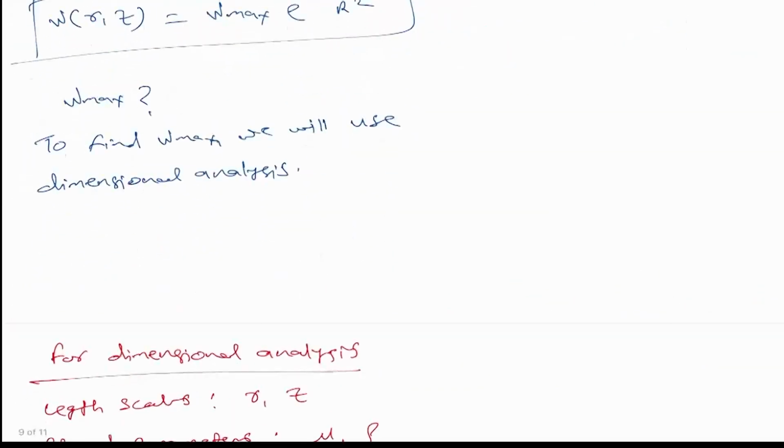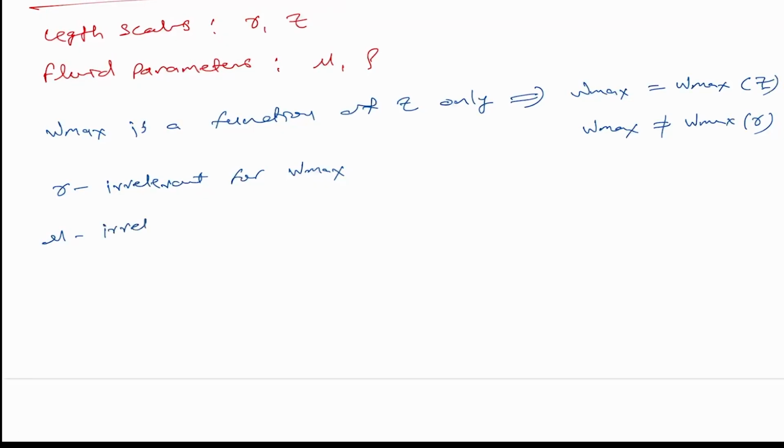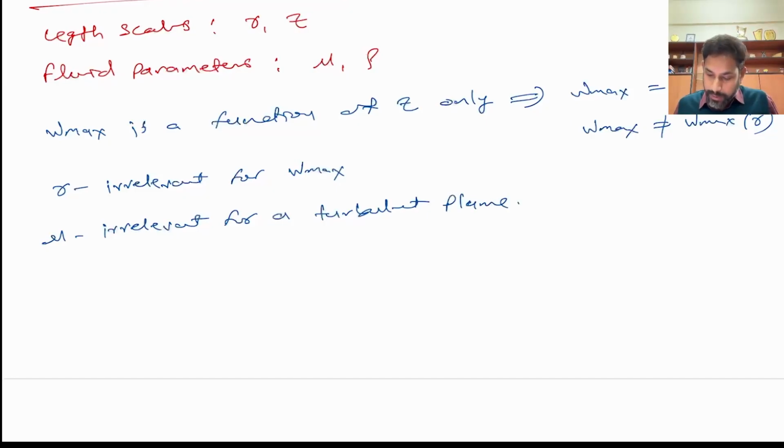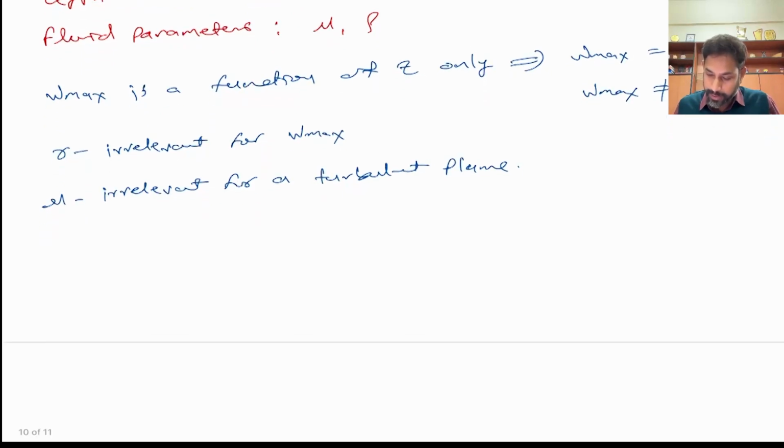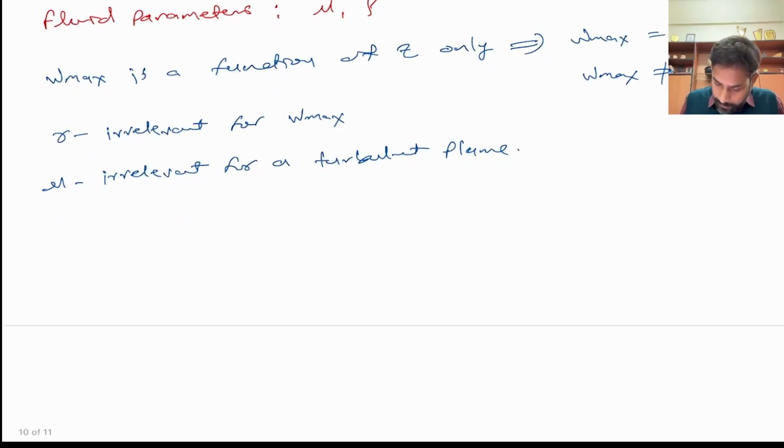and because of that, in this formulation we will consider that mu is also irrelevant for a turbulent plume. Okay, so now basically we are trying to balance inertia force only with the buoyancy force. So rho basically represents delta rho, which gives us G prime, and also Q, when you multiply we get B, right?